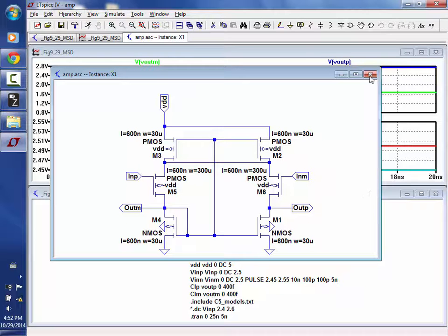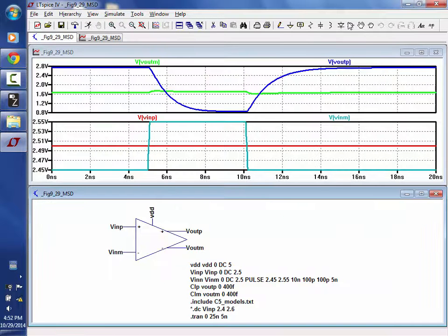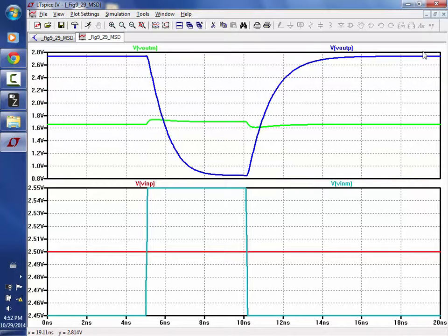So what I want to do though is determine the DC gain here. And the other point is it's fast. When you're doing your designs, you need an amplifier that has fast settling time, or else you're not going to ever be able to keep up. It's like you dumping the water in, but it takes you so long that the decisions that the people following you make are just irrelevant nonsense. You need fast settling time, okay?